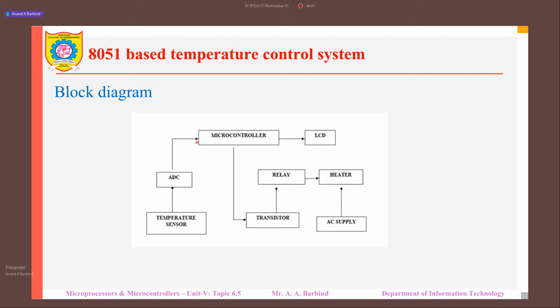That particular command is called start conversion. The ADC has an input called start conversion, and that pin is usually labeled as SC. After the start conversion signal has been given by the microcontroller to the ADC, the ADC starts converting the analog input from the selected channel to digital data. After it has been converted, its output is ready.